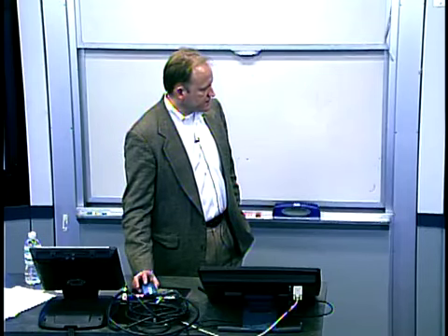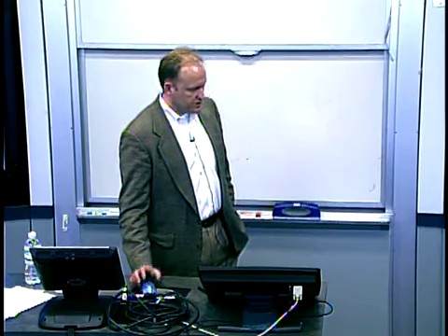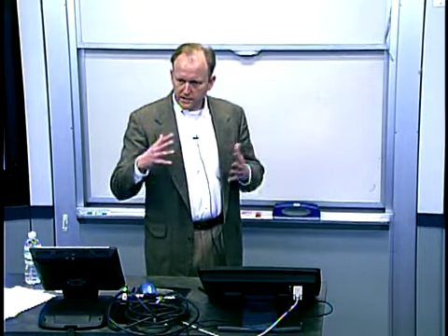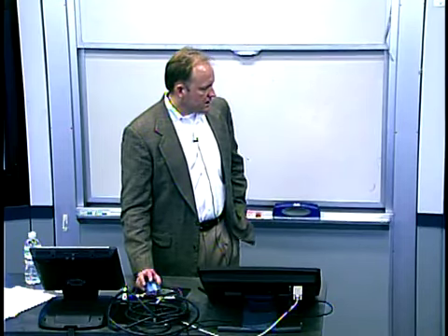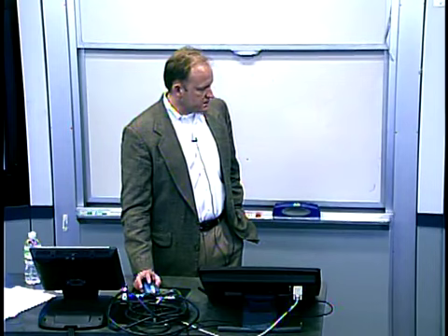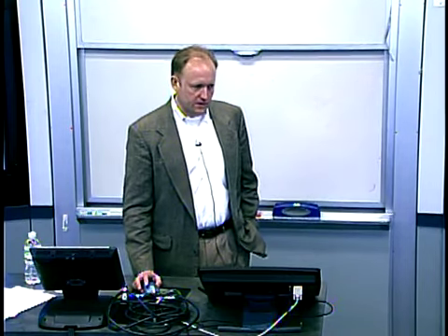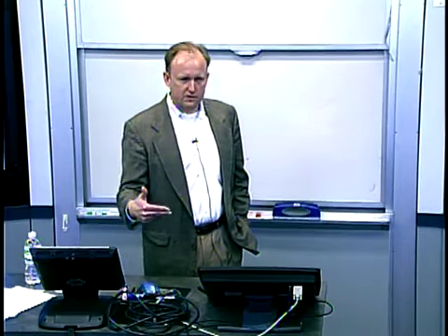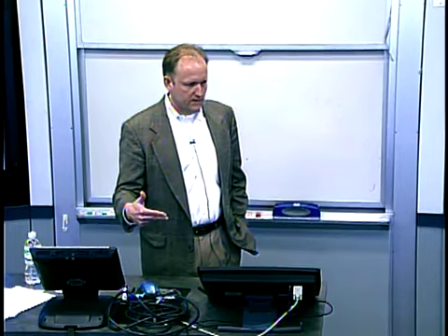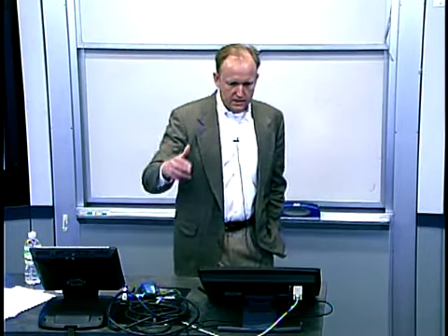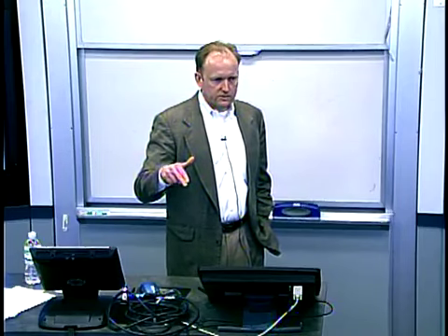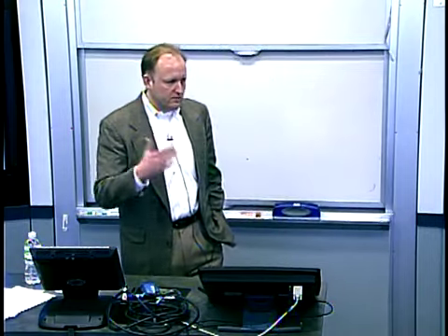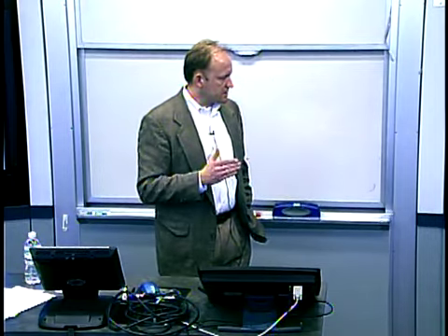The reason we think that one is interesting is that I alluded earlier to the idea that we are doing big studies of complex systems and regularities. One of the things we found is that interactions being about a quarter the size of main effects is pretty typical. If you go into a factory and get your engineers to list the factors they're interested in studying, and then run a big experiment and study some of the interactions too, you will generally find they're about a quarter the size of the main effects. It's a reasonably reliable regularity, and so we think that's typical.